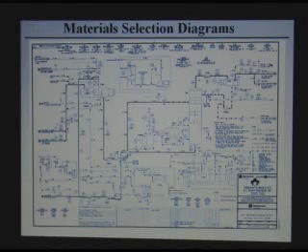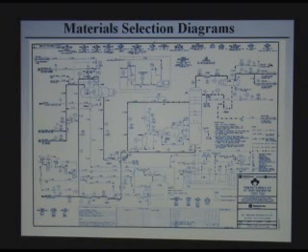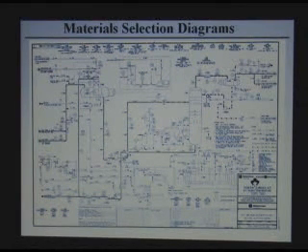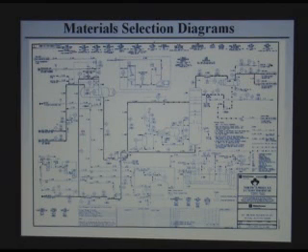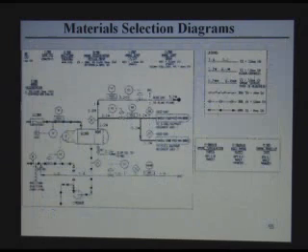And for piping, we give a designation on each line, and in the key here, we explain what it is. And here in the notes, we give the special requirements. So this is a typical example of a material selection diagram. By just one look, you can tell where we have carbon steel, where we have stainless steel, what special requirements, stress relief, no stress relief. So it's a very, very useful tool for project material selection, preparing specifications, data sheets, and everything else.